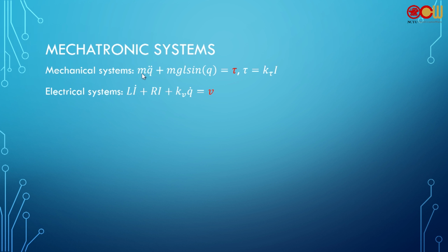We cannot say, oh, give me this torque and you can achieve that torque. In other words, the torque is a function of current. Ideally, torque is proportional to the current in the circuit of the motor, right? So there's another electrical system to formulate how, given a voltage, you can generate the current. But it's not simply a proportional relation. It's an ODE, a first order ODE.